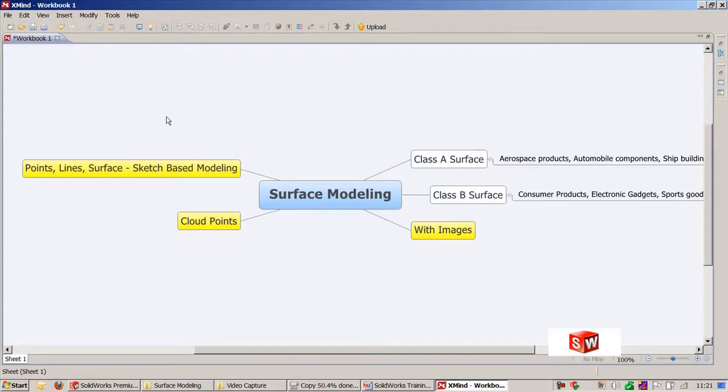But creating that sheet metal in the sheet metal design environment will not be the solution, because the output we need has a number of curvatures and tangency continuity in the whole design. That cannot be achieved using sheet metal design, but it can be achieved only using surface modeling tools. So what is the requirement? Once you complete the surface model, that will be used to create core and cavity.